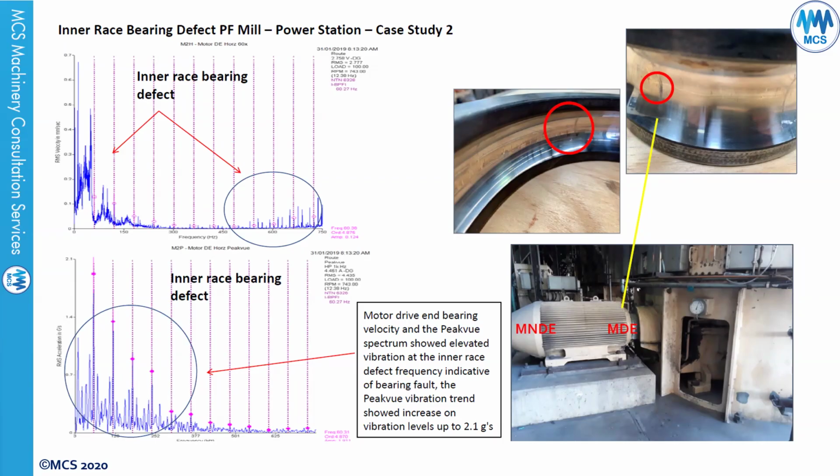That's why we need to do routine data collection. And that's why, when we see that the bearing is in stage 2 or stage 3 and we start to see some changes, we can increase the frequency of data collection to keep an eye on it. That's why our recommendation is to monitor this bearing at a shorter interval, especially if the machine is critical, to be able to capture any changes or deterioration between every 2 measurements.